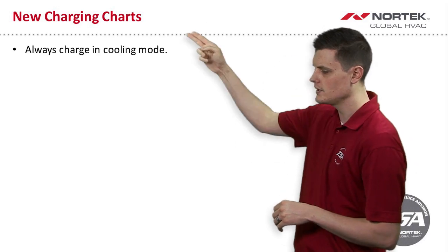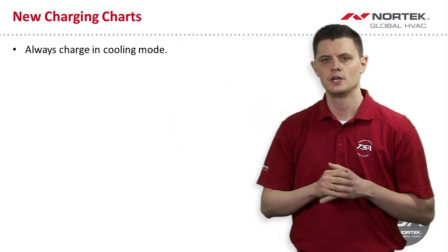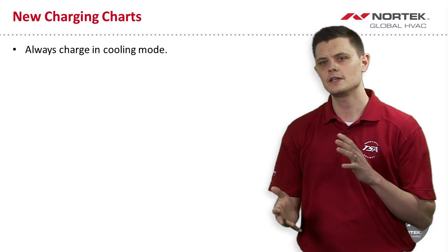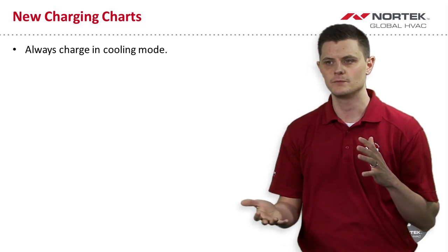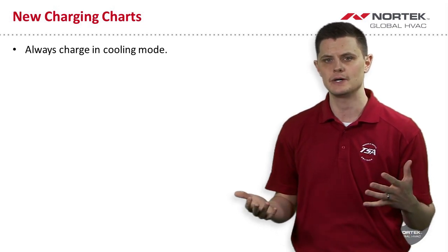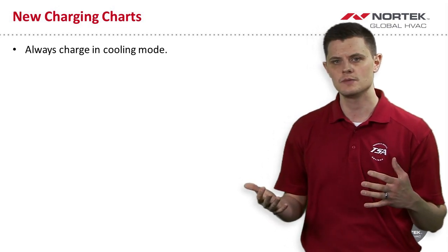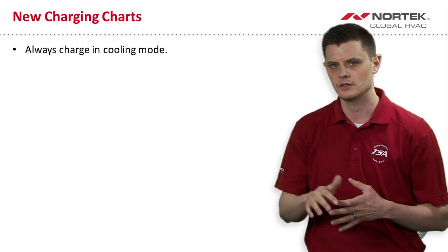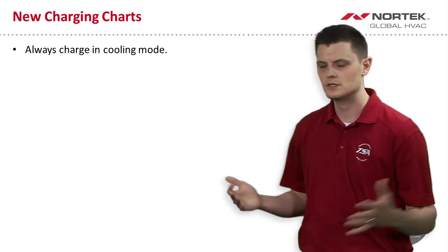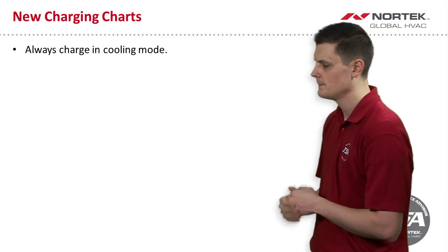One, we will always charge in cooling mode. So even if it's 40 degrees outside and you've got a heat pump and we're trying to charge this thing, we're always going to be charging it in cooling mode. We'll get into that in a little bit here. But just to start out, always charge in cooling mode.